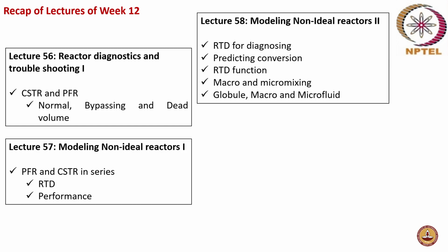The next lecture was on modeling of non-ideal reactor again. Here, RTD for diagnosing was discussed, where the mixing, bypassing and dead volume, and the exit conversion were all discussed when kinetics is known. And then predicting the conversion. For predicting the conversion, the RTD alone does not help. It requires a model and kinetic information to identify the exit conversion.